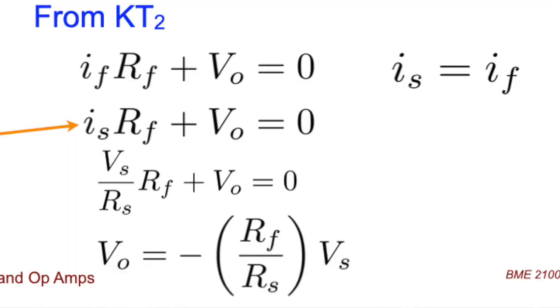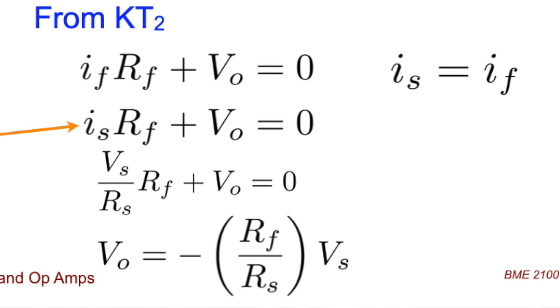And then I have the amplification factor, that A that I was looking for before, right? The A of the whole amplifier from my bioelectric measurement circuit. And that's going to be this ratio of the feedback resistance and the source resistance. So this gives me a very simple way to tune or set that amplification that I need for my application.